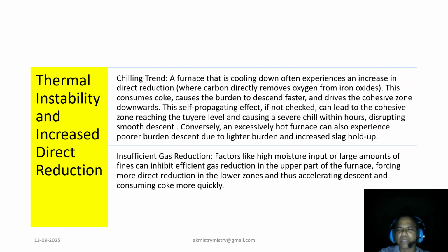This leads to cooler output, may also burn tuyeres as the cohesive zone becomes very near to the tuyere, and many times the backflow of cold metal and slag in the blowpipe has been observed in different furnaces.